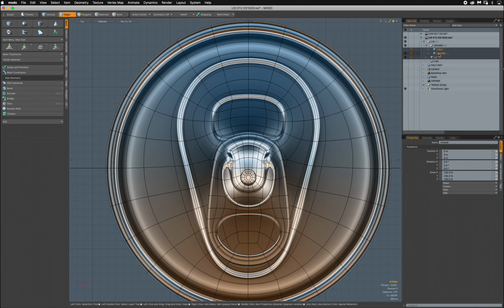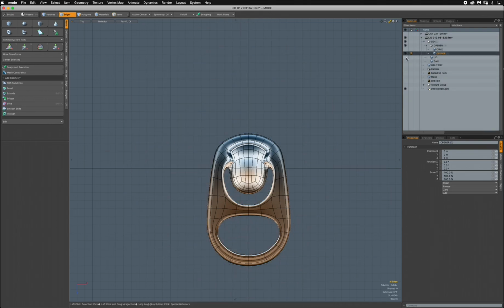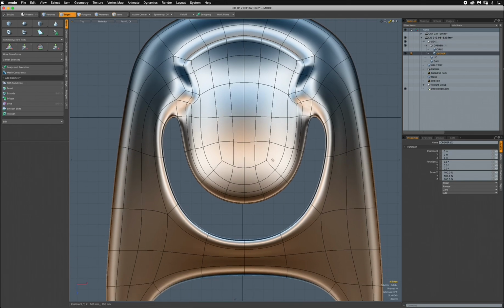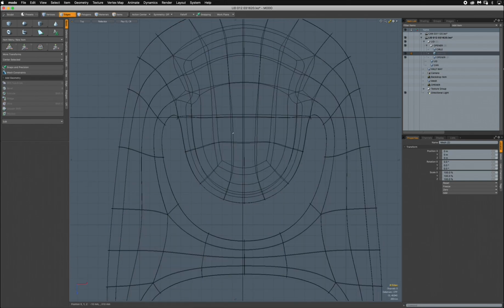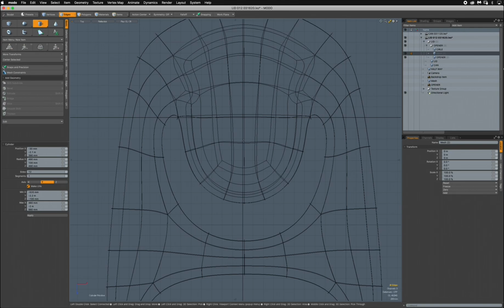It's basically you could just deselect everything, say a new mesh, go to this cylinder, go to this position here where the cylinder goes. You can make the size 12. It doesn't have to be that big because it's small. And just make sure this is somewhat round, the numbers 285, 285, you know, within reason.